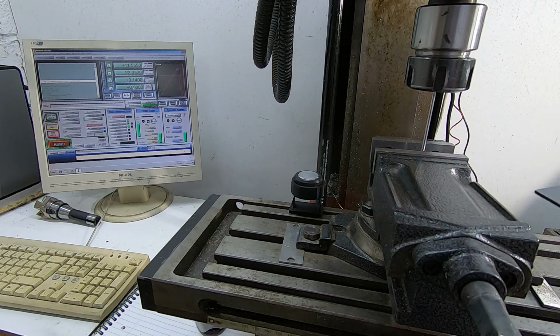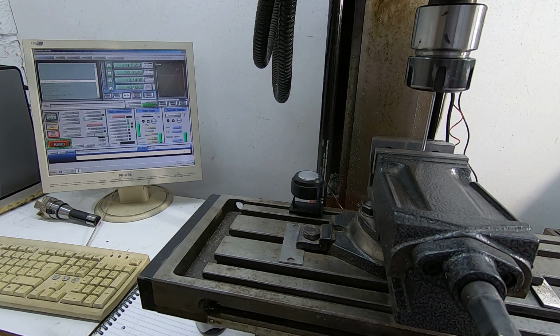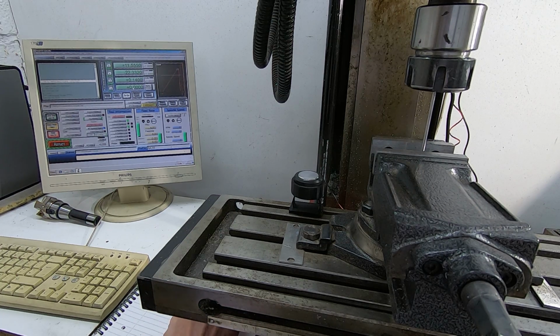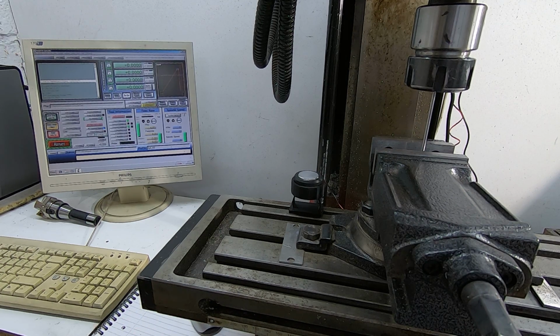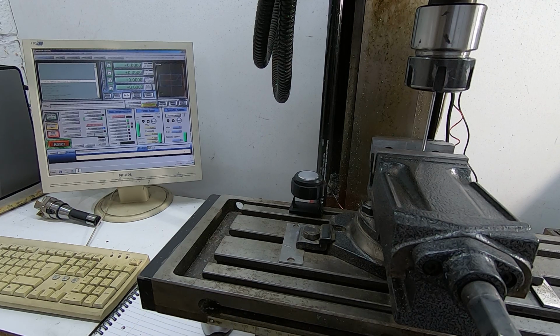I'll take that out. The reason I'm doing this is because I want to kind of simulate a milling operation, and obviously that will entail the tool moving downwards. And what we do now, of course, we've zeroed to where we want to start the milling operation. Pretend we've bolted or clamped a piece of stock material into the vise. We zero the G54 fixture. So we zero X, Y and Z. I don't know if you can actually read what's on the PC screen. And if we now regenerate the toolpath, we should be able to see what we intend to mill, and we can. That's now come up quite clearly.